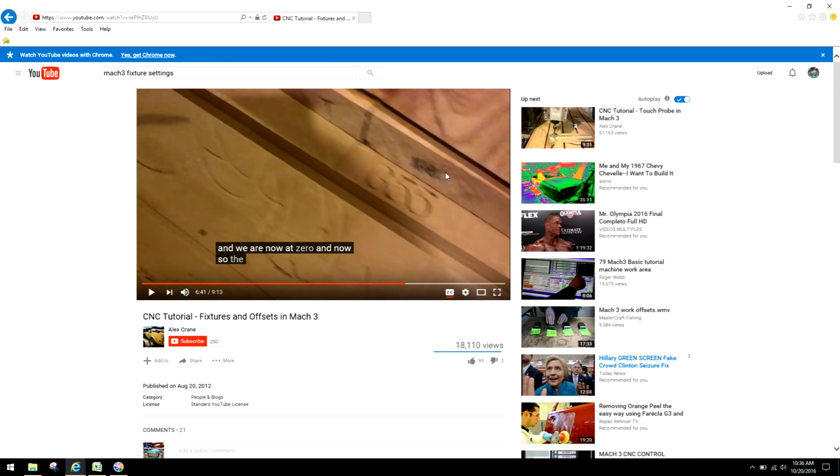Like I stated earlier, and this now should really make a lot of sense to you, where I was discussing the jigging aspect. If you use some aluminum angle or just aluminum in general, once he does the engraving in the table, he could then make the width the same width of the engraving in the table, insert that piece of shim, and then line everything up more or less like a saw fence on a bandsaw, or any saw for that matter. The idea is to keep your pieces perfectly square, keep everything in the exact same location, and all you're doing is basically loading and removing raw material as it's machined.